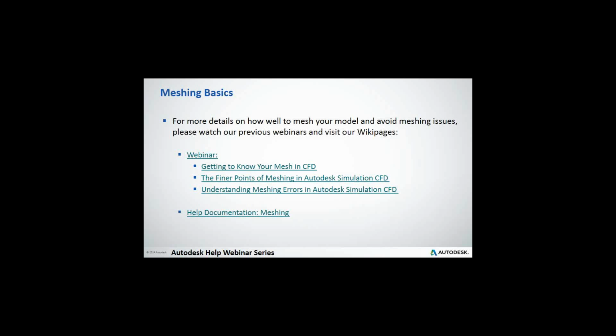Exactly. Another note about the meshing basics is, we showed a linear graph, but eventually it will go non-linear, and you'll just be spending more time on solve. Your results will not be getting any better. So that's kind of the trick. I generally say, the best mesh is the coarsest one that gives good results, because time is important. So figuring out where that point is, is the goal of today's webinar.